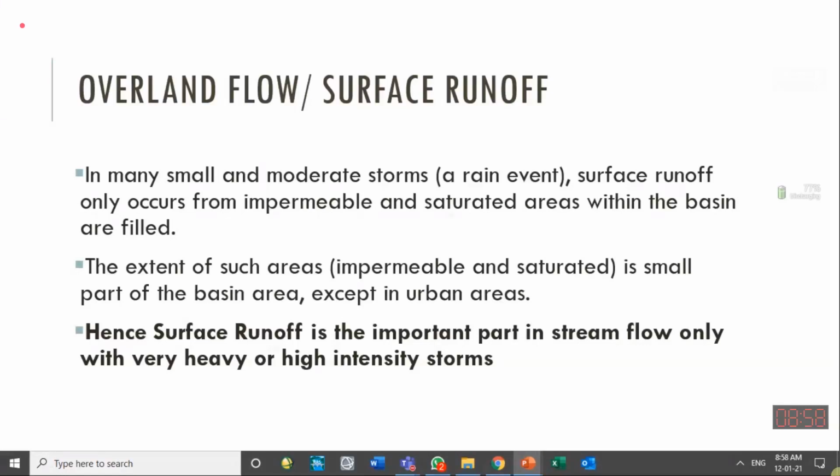From here I will tell you something practical from life. People ask: what is the benefit of grounds in the urban environment? Usually, the grounds in a housing society like UET or other societies are kept at a lower elevation, and they have a special name. We call them Doongi Ground. The local people will understand, Doongi means low elevation. So the rainfall water is collected in that low-lying ground, and it infiltrates over a few days after the rainfall. That helps us maintain the groundwater.